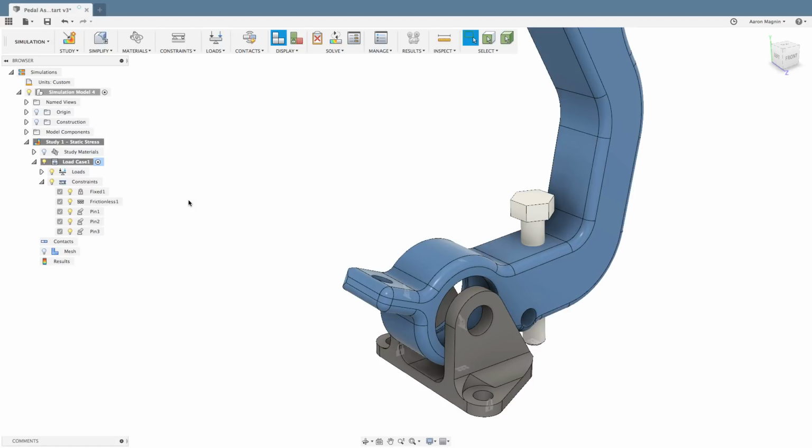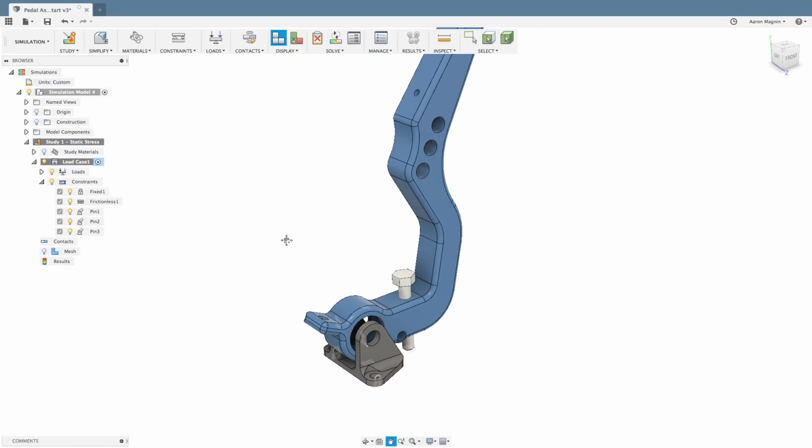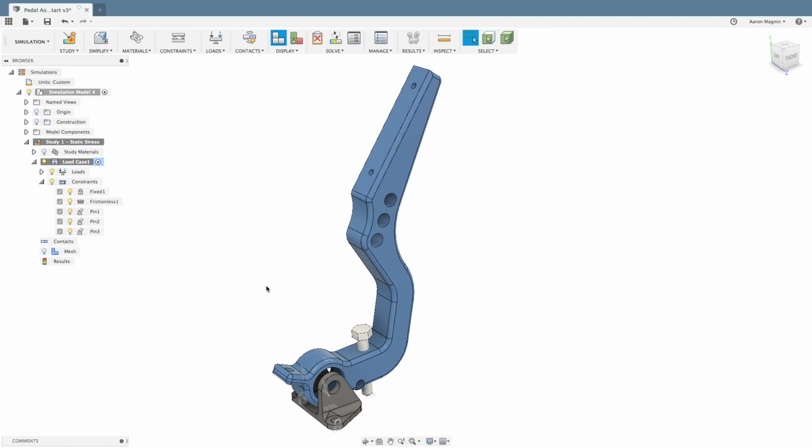That's going to be related to each one of the faces that I selected. So we're not necessarily pinning these faces together like you might do with a bolt or something. In this case, we're just pinning those cylindrical faces, getting rid of the movements as described in the previous setup. Okay, so we'll continue on, and I think the last thing, and this is probably the easiest thing for people to visualize and to understand and to apply. This is where you actually apply the loading situation.